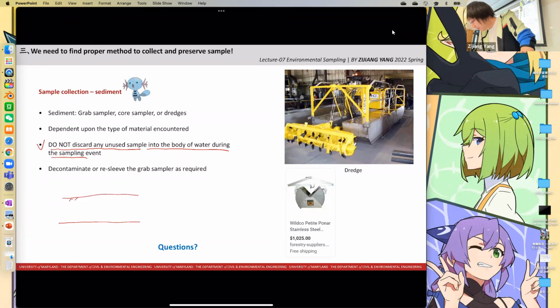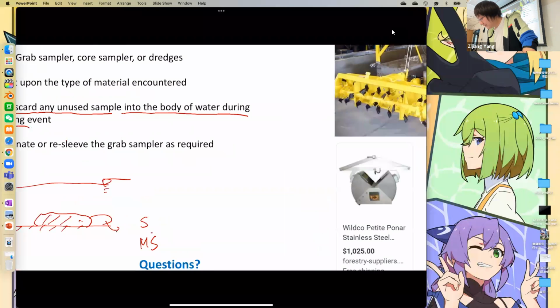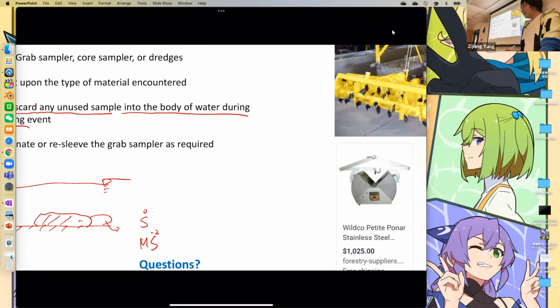Let's say this is the water phase, and here we have the sediment. The sediments are under the water, so there is usually no oxygen in the sediment. Let's recall when we were talking about acidity: in the sediment we may have sulfur or some metal sulfur salts. Here M refers to the metal, and the sulfur is at -2 and this is 0. They are stable in the sediments because there is no oxygen to oxidize them.